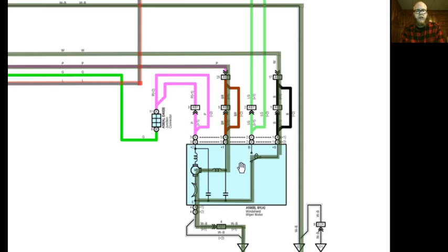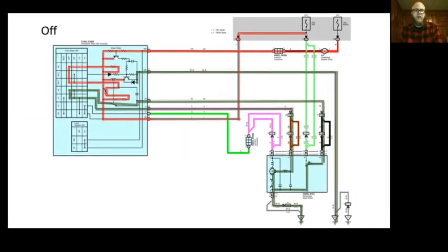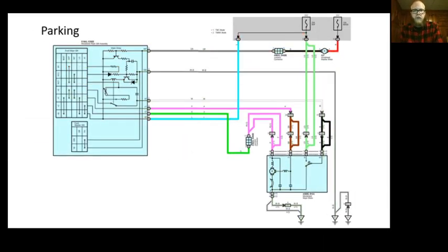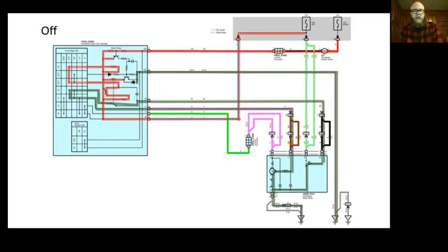But if I shut off the wipers while they're halfway through their travel, this switch is going to be connected to this wire until the wiper comes all the way back. And we're going to see what that looks like right now. This is called parking. And so here I was off. Let's say my wipers were in the middle. And this would happen even if I turned the car on. Like, let's say I shut the car off, the wipers are in the middle of the windshield. I don't care. I get in the next day, turn the car on, it's sunny outside.